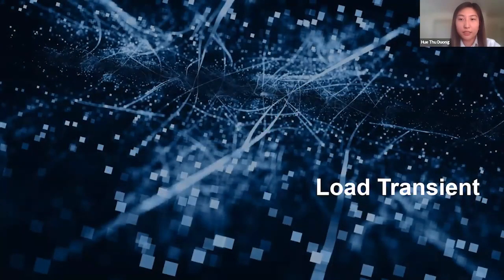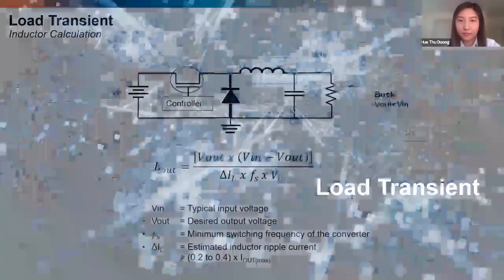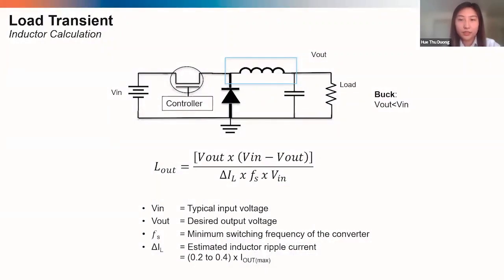So next is our final topic, which is load transients or load fluctuations in the circuit, and we'll go over how to handle such situations. Looking at a circuit for a controller, we'll need a bank of capacitors on our output to act as a reservoir of capacitance for any possible transient events.